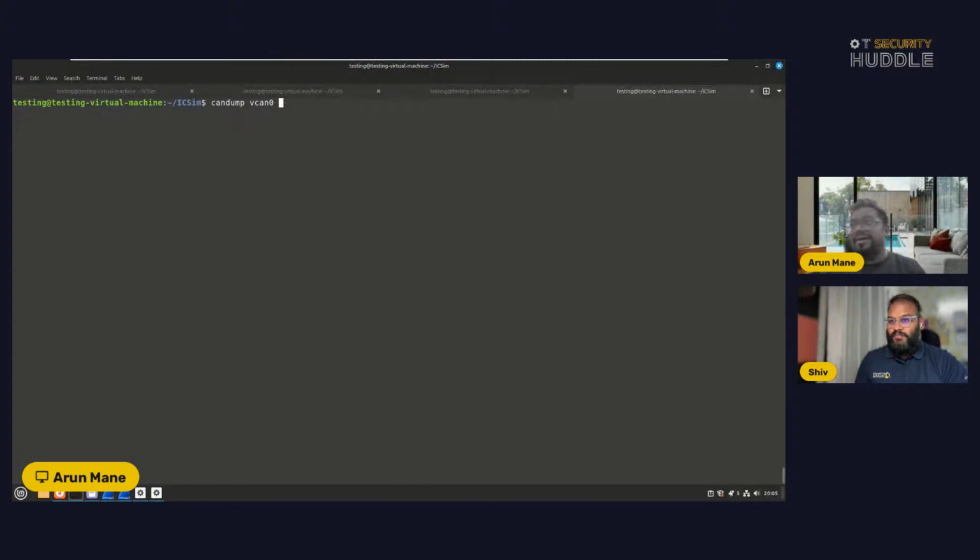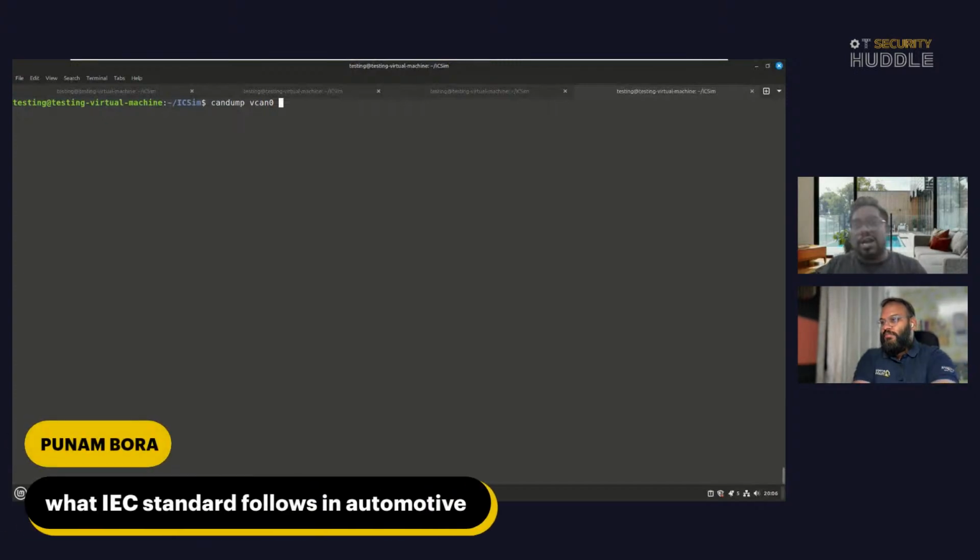Now we can perform that bus-off attack. It creates a bus-off situation. And in that situation, fuzzing, or rather sending those kinds of errors continuously, converts into a long-time bus-off attack. The entire communication goes down. But from the developer's point of view, they have to decide how many errors they can receive, and based on those errors they have to mitigate the problem.